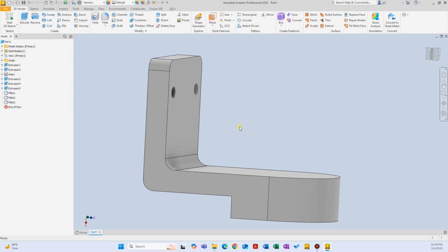One good example would be the windows on an airplane. The corners are always rounded, right? Because if it's a sharp corner, a crack can start from those corners. That's why they design it in a way, they use these round edges and corners to reduce that risk.